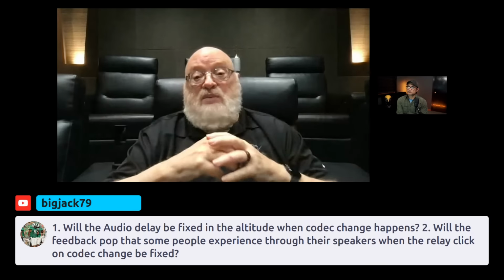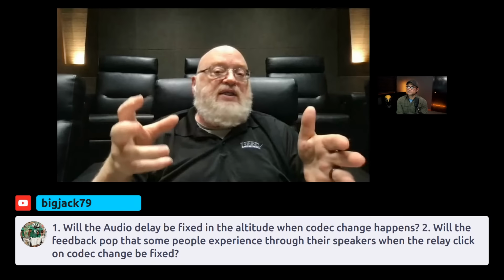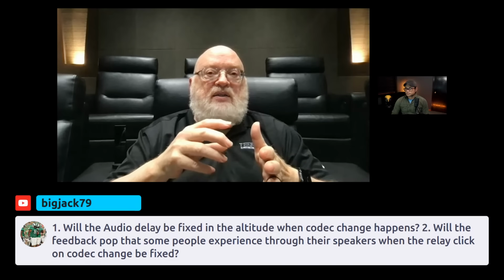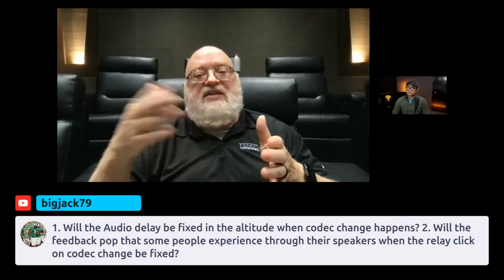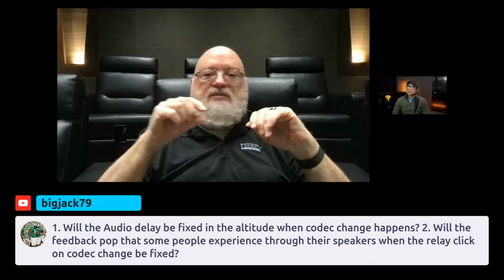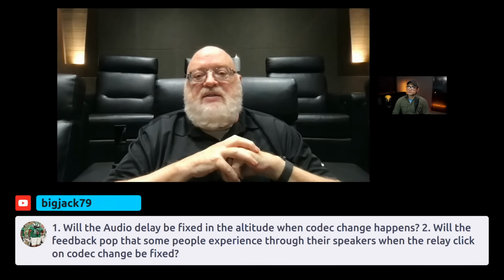And that's pretty much what the relays are doing. Now, we're doing it specifically to avoid nasty noises that could otherwise be created. But depending on the input stage of the power amp that you're using, and maybe the sensitivity of your speakers, if they're really high sensitivity, so even a tiny little signal is reproduced audibly, yeah, it does happen.